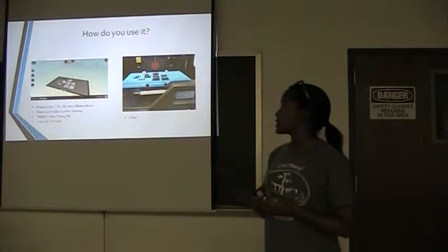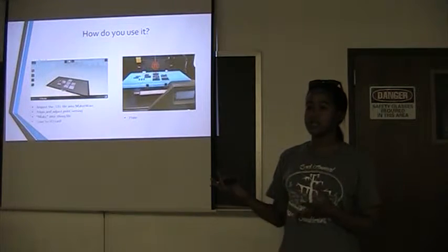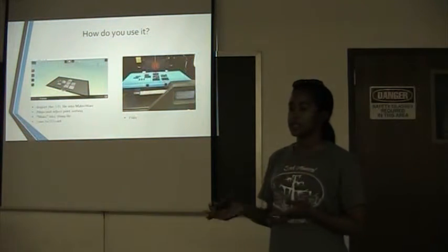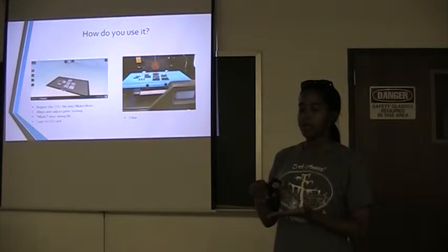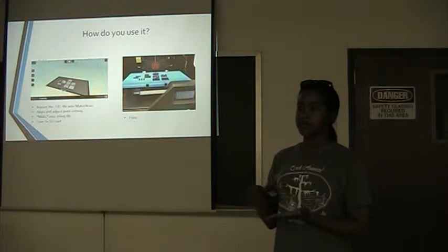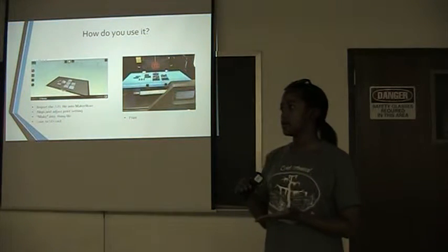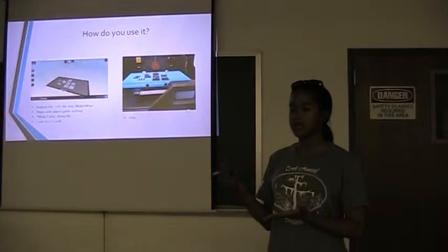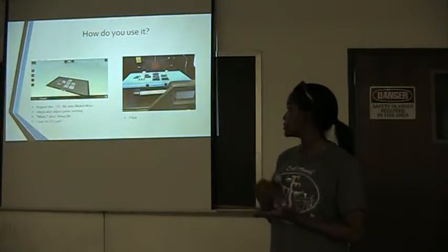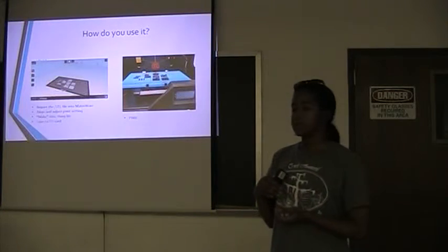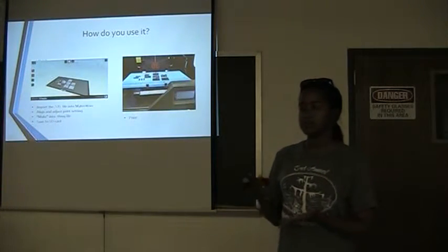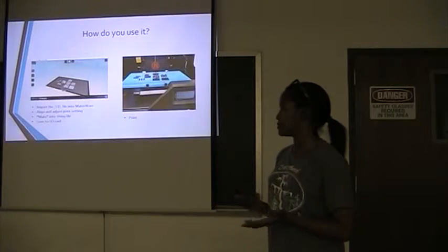And basically how it works is you've got a spool of plastic in the back of the machine, and it melts that plastic and prints layer by layer using a nozzle. By the time the plastic is on the build platform, it's cooled down into a solid piece of plastic.